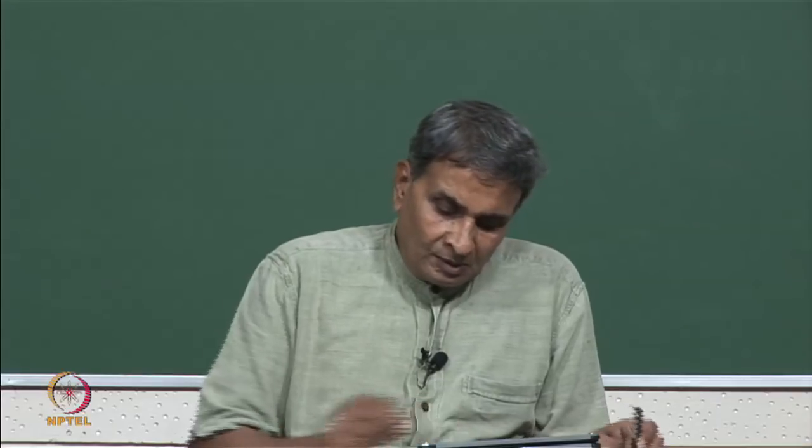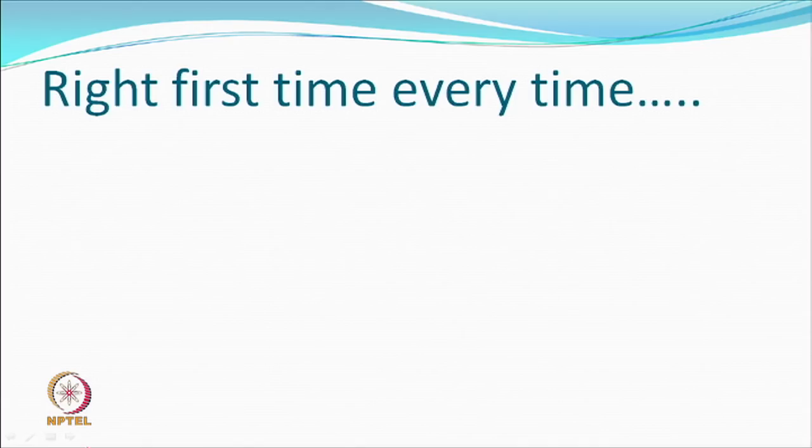Therefore, one is looking at printing as an operation, coming to all the unit operations that you saw. This has to be right the first time. There is nothing where you can say, well, it does not matter, we will try to repair. When you do something wrong in dyeing, say the depth of shade that you wanted is less, you can top it up. It costs, but you do not have so much wastage, you can top it up.